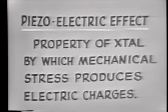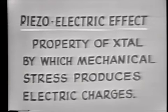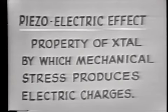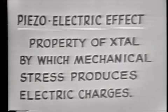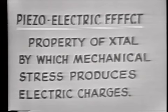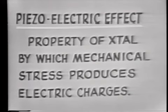There are many types of crystal substances, but not all are suitable for use in oscillator circuits. A crystal used in oscillator circuits must possess a characteristic known as piezoelectricity, or the piezoelectric effect. Let's look at a definition of the piezoelectric effect. The piezoelectric effect is defined as the property of a crystal by which mechanical stress produces electric charges, and conversely, electric charges produce mechanical stresses. At this time, you should complete item 1 of your TVI guide.